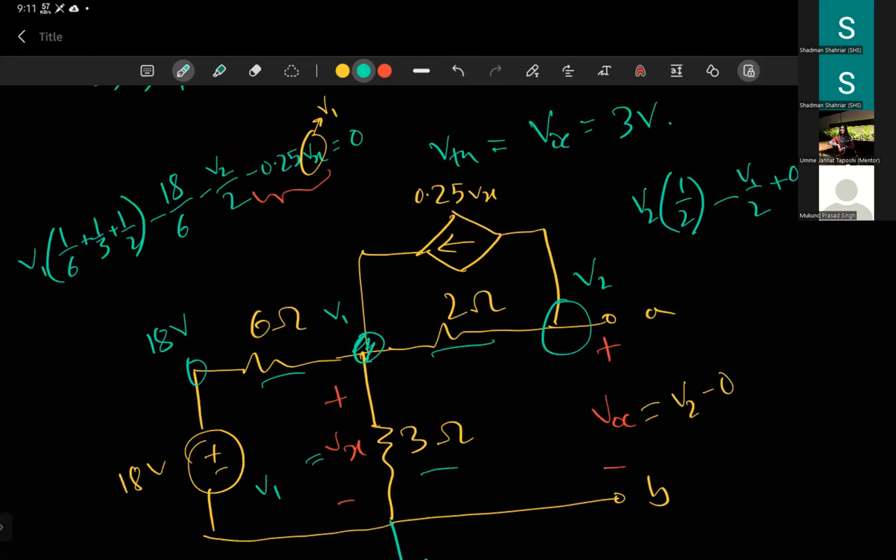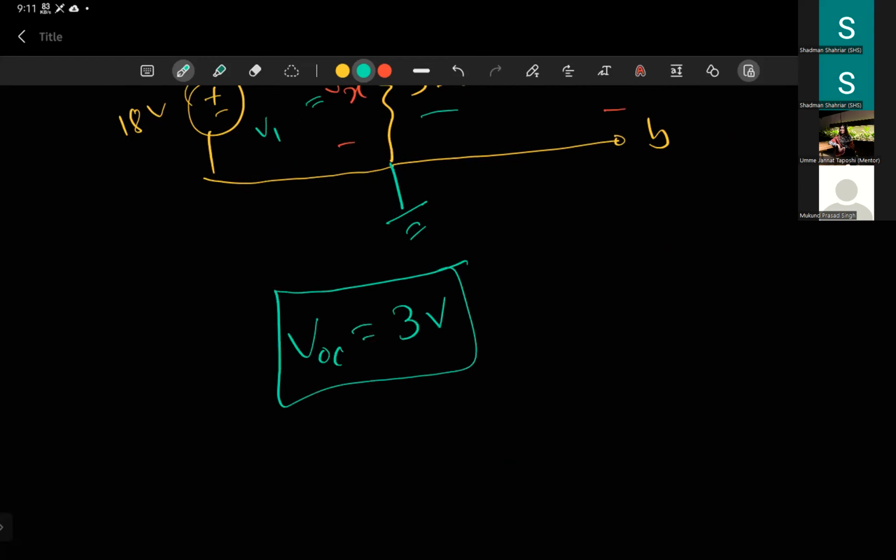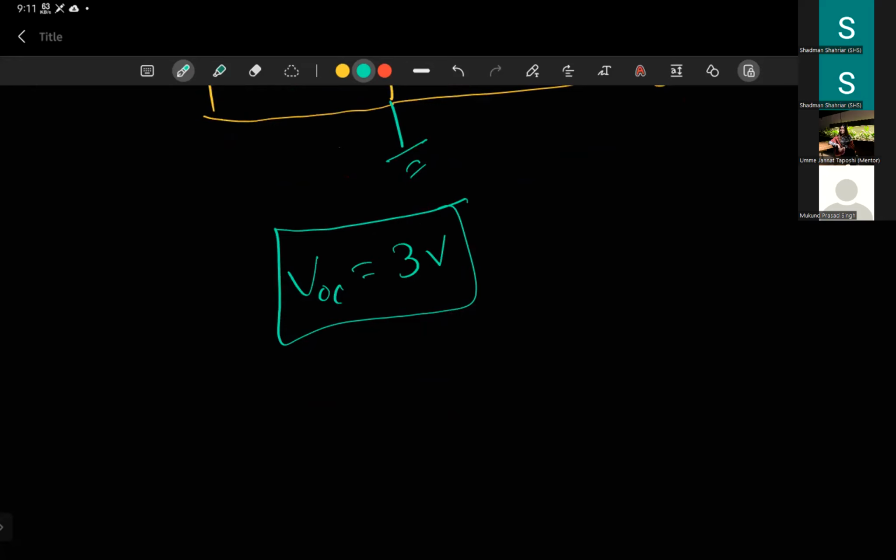Okay, there is one other scenario here. The 3 volts here, so the Thevenin voltage is 3 volts. If you have a non-zero VOC, you can find the short circuit current, right? You need to find ISC, and then you can find RThevenin by doing VOC by ISC. Since VOC is not equal to 0, we will do short circuit current.